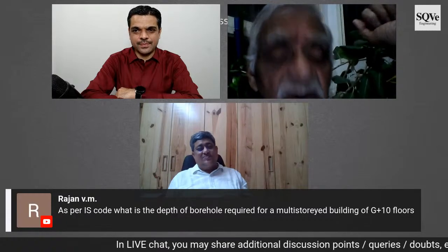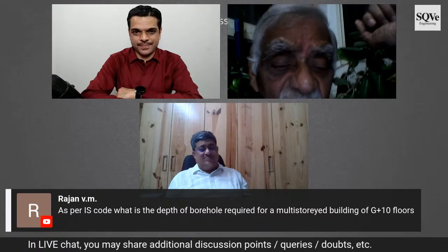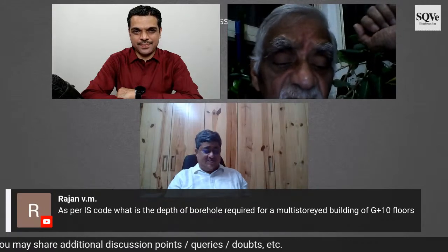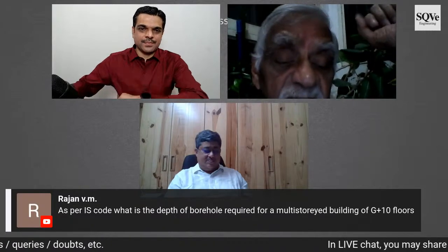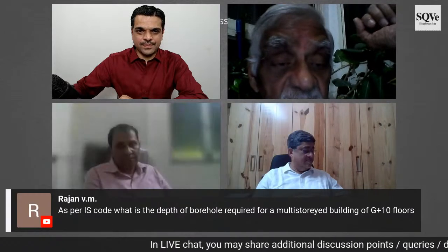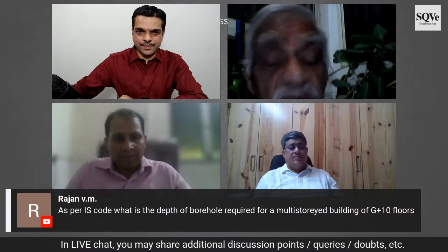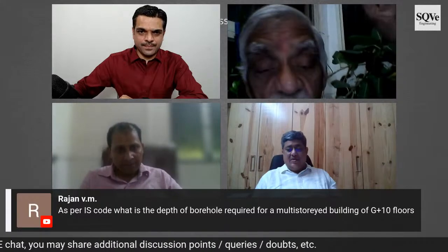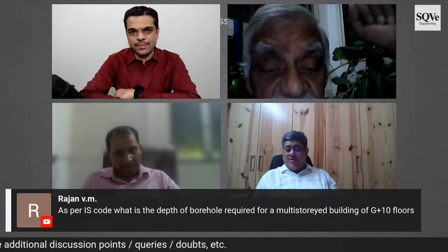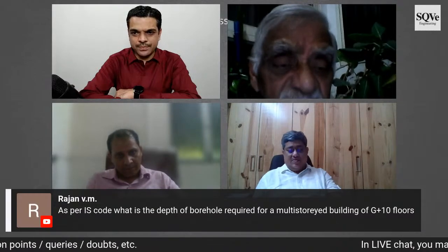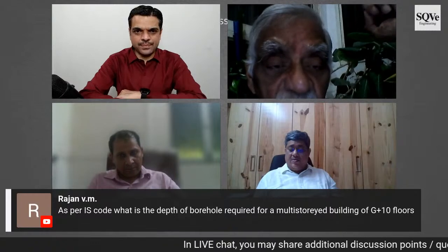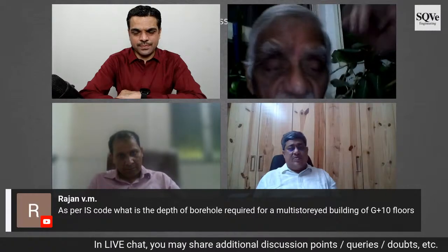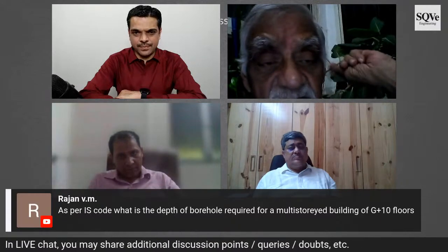That is true. For a commercial building, go ahead with 1.5 ton per square meter. There are certain areas, like cold storages, or printing presses, which have improved nowadays. But we used to take 2.5 ton per square meter for places like paper mills, where you store paper. The load on the slab can be 3 ton per square meter. So obviously you generate your own thumb rules, and that will give you a path to identify what is to be asked for. That is the point that I'm trying to make.